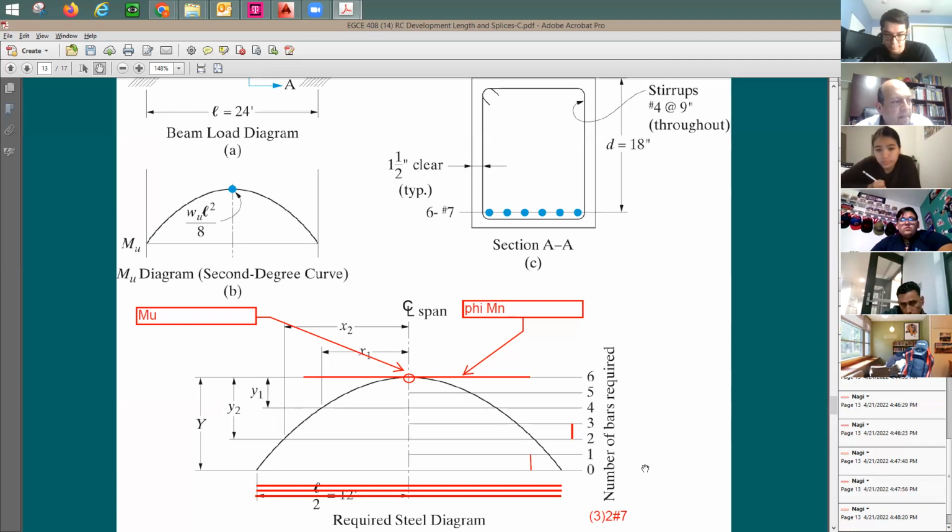Okay. Can I keep them straight from the beginning to the end of the beam? Is this okay? Do you think my beam is going to be safe? Say yes, no problem at all. You can just put 6 rebars here. You just cover it, because when you get to the point of maximum moment, you'll provide enough phi Mn for it based on these 6 rebars.